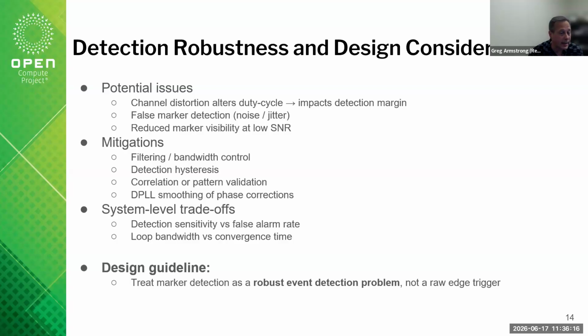You can detect hysteresis, like maybe that pulse per second signal jumped from one cycle to the other cycle, which is like a 100 nanosecond jump. You can sit there and say, well, is that real, or did whoever's embedding that maybe just mess up and get it on the wrong cycle, and it comes back, right? So you can put in hysteresis detection because you still have the 10 megahertz clock to say it's very difficult to steal cycles away from a clock, right? And it's very difficult to go something like backwards in time on a clock as well, right? So even if it did maybe shift backwards a cycle, right?